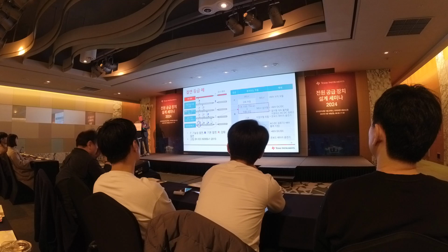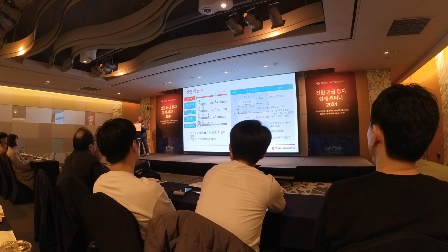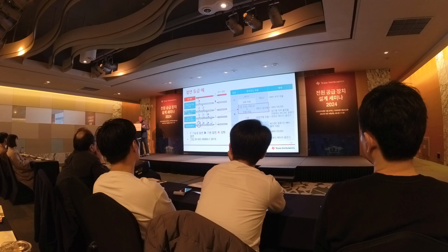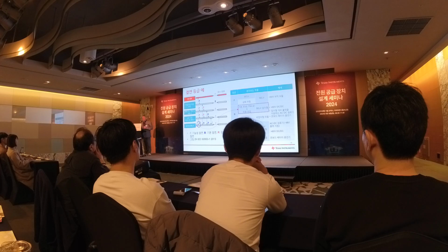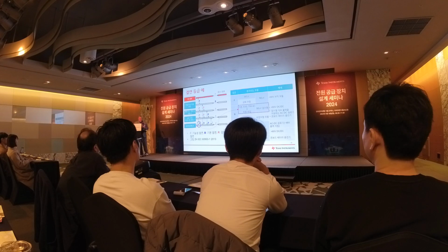And then for the reinforced insulation, we have more examples shown here as well. Whether it's primary or hazardous voltage to a safety extra low voltage that's earthed, or between a primary circuit and a reinforced part, this also needs to have reinforced insulation as well.